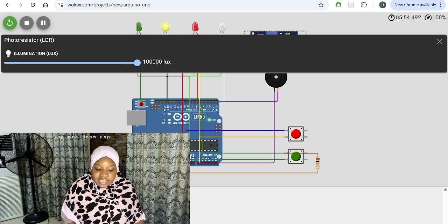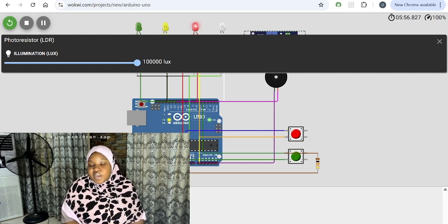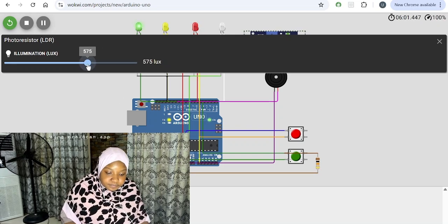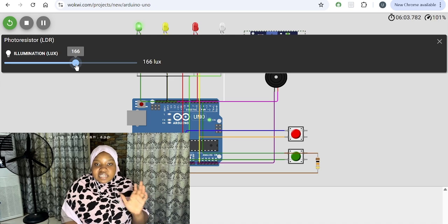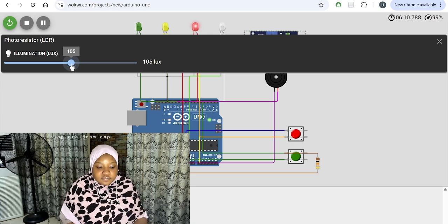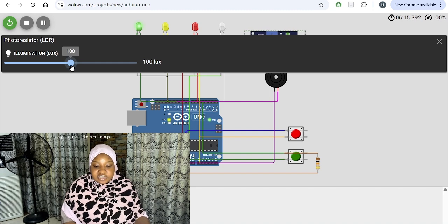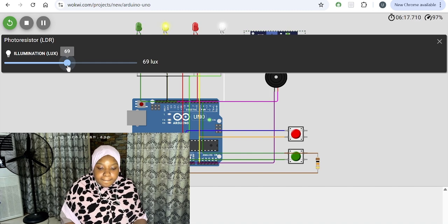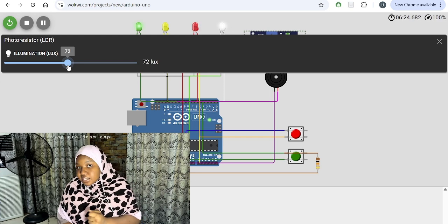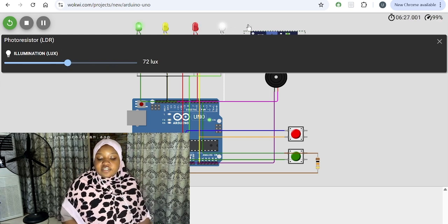And we have 8 here. So with these two, I add them and divide by 2, and I get 512. When it's anything below 512, so 511, immediately our street light system would work. So for instance, this is 511, and then our street light is on. So below 512, rather, that's our threshold for the system.